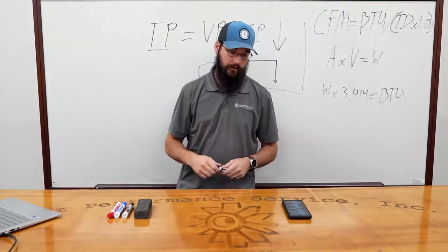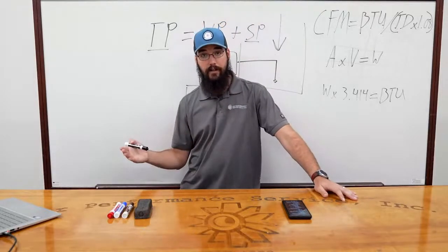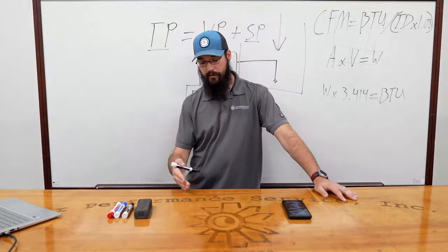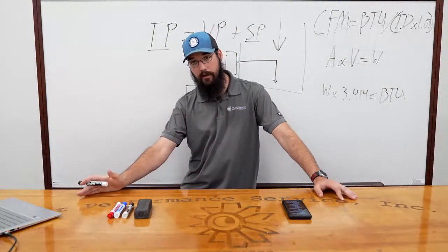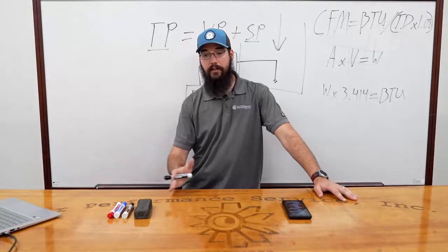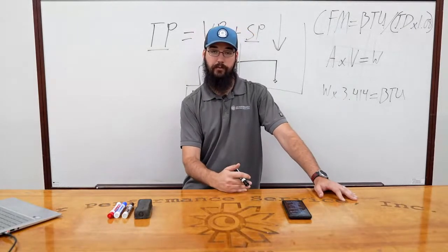So that's one consequence. Another would be elevated saturation and superheat. You may end up pushing so much air through that coil that the TXV has a hard time feeding enough refrigerant to it.